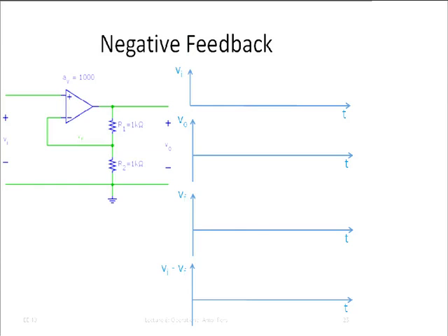All right, so here we have a feedback circuit that actually is an electronic feedback circuit. It uses an operational amplifier. Let's suppose that we start here, that we initially, let's say, the voltage Vi is 0, then the voltage Vout is also 0, and then the voltage Vf is 0. But now let's suppose that we put in 1 millivolt, okay? So we now set Vi equal to 1 millivolt, while Vf is still 0, and consequently Vi minus Vf is 1 millivolt.